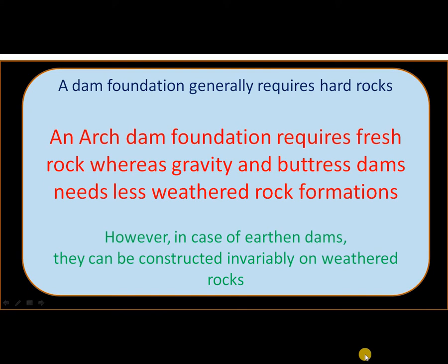Dam foundation generally requires hard rocks. There are varieties in dams: arch dam, buttress dam, earthen dams. In case of arch dam, foundation requires fresh rock, whereas gravity and buttress dams require less weathered formations. However, in case of earthen dams, they can be constructed on weathered rocks.